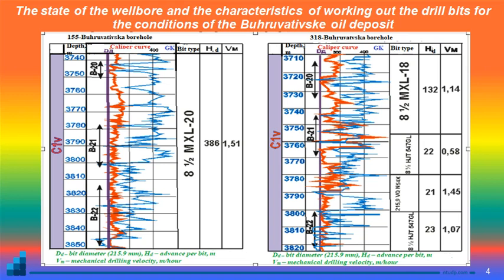In the conditions of the borehole deposit, associated with a group of structural highs, disturbed by discharges, stratified, vaulted, tectonically shielded and lithologically limited deposits, it was determined that with an increase in mechanical velocity and bit penetration in unstable rocks, the cavernousness of the wellbore decreases, and this prevents the occurrence of various complications: violation of the integrity of the borehole walls, the attachment of the drilling tool and the casing strings. This also helps to reduce the consumption of drilling flushing liquids and tamping solutions.